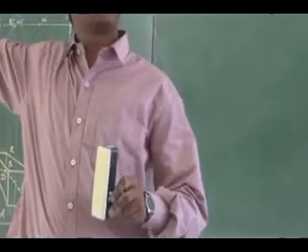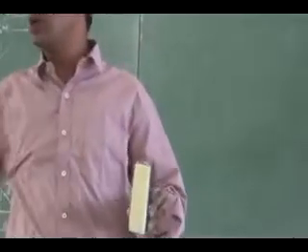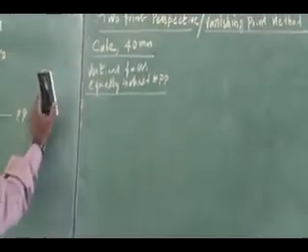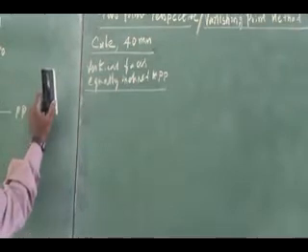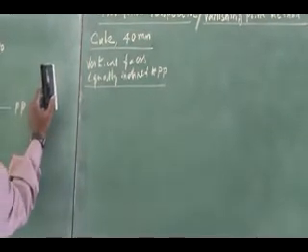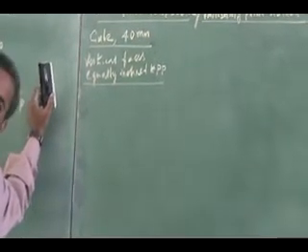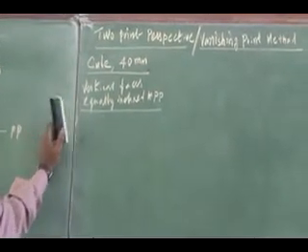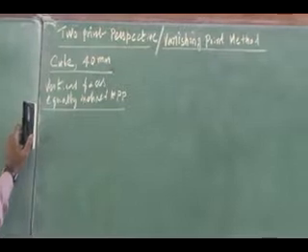So far we have seen the solid's face parallel to the picture plane, where I can go for a single point perspective, that is the vanishing point and visual ray method. Now the vertical face is equally inclined to the picture plane. Even here I can go for single point perspective with the same old procedure. But if I go for 2-point perspective, it will be more realistic.